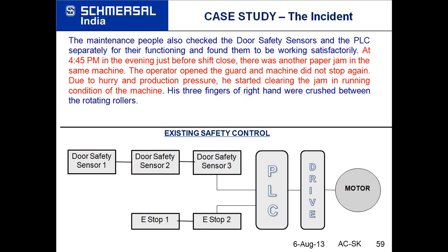Now we will analyze what was the problem in the connection of this. When I say the door safety sensors, these were of safety type. When I say emergency stop, these were of the safety type. PLC was not of a safety type, it was a normal PLC. Drive was also a normal drive, and motor everyone knows.